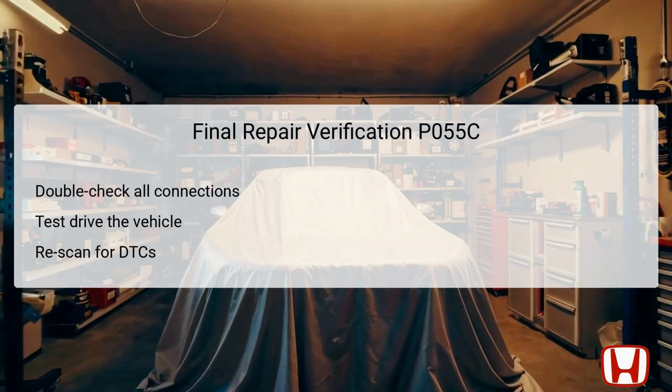After completing all necessary repairs and replacements, it's crucial to conduct a final verification to ensure that everything functions correctly. Begin by double-checking all connections associated with the rocker arm oil pressure sensor and the PCM to make sure there are no overlooked loose terminals or poor connections. Following this, the vehicle should be taken for a test drive, which will allow you to monitor performance and make sure that the issue does not reoccur.